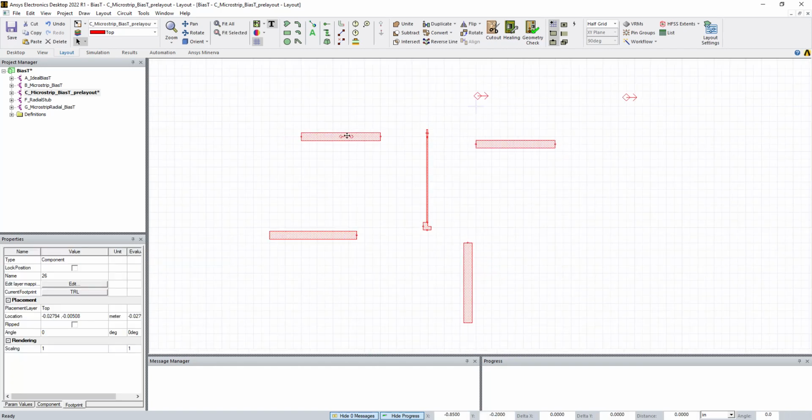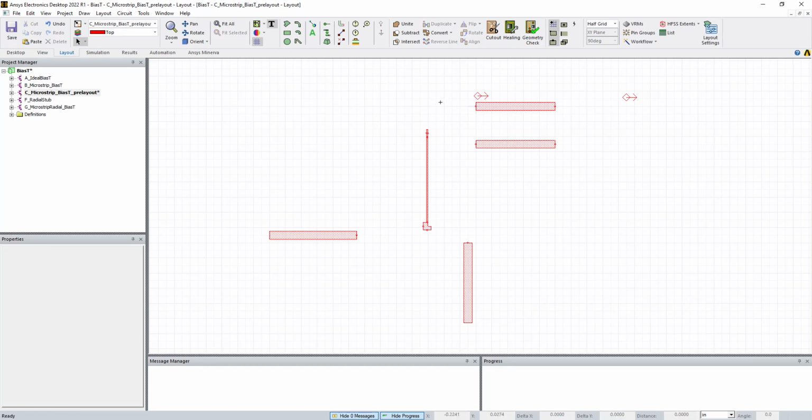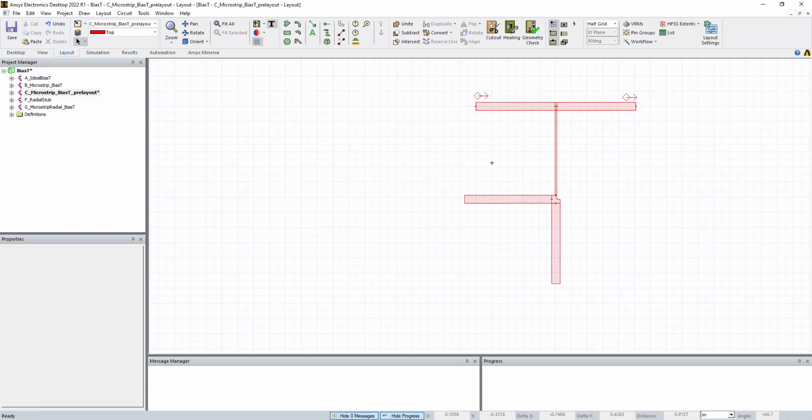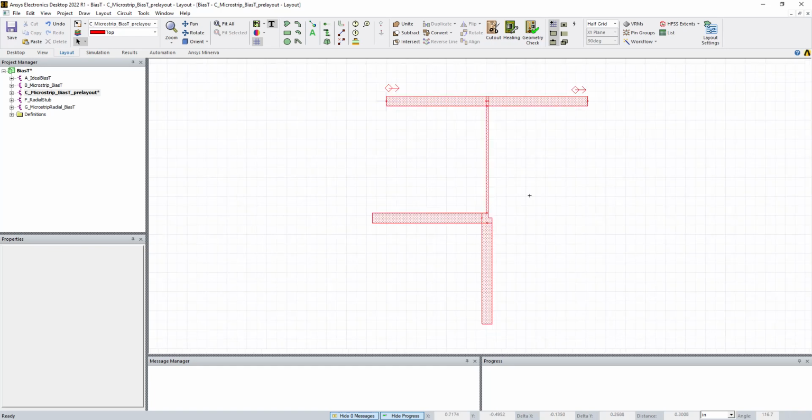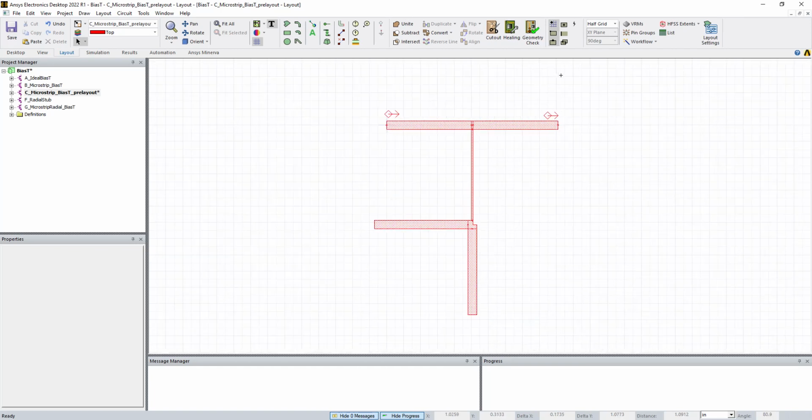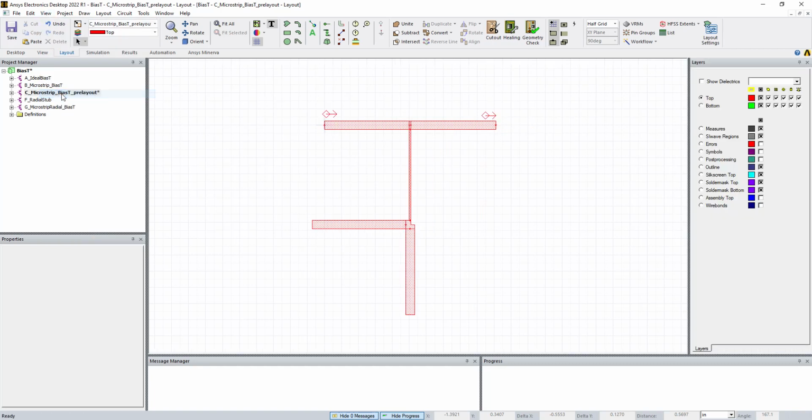So what you're going to do is click this leftmost point. We're going to say its location is 0, 0, and it's the location of the leftmost center insert spot. Then I'm going to lock it there, lock position. So I'm locking this one to start at 0, 0. Then press the Control key and M, as in Mike. Control M realigns all of the components to start right at that point. All right, so that's our step one. Let's get it all aligned. Step two is we're going to go over here and say View, Layers, and Show Dielectrics.